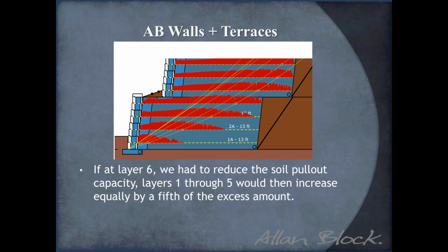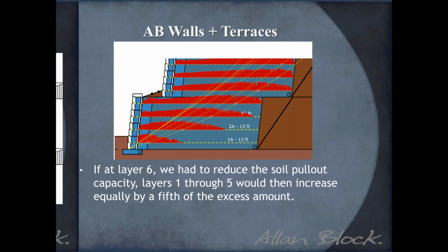So each one of the T requireds for the other 5 layers will increase by 100 pounds, so that all of those loads are put into that baseline solution, and now the new T required at these locations will reflect that additional 100 pounds. So it's pretty straightforward, I think. I'm hoping that idea is being passed along. That's how we're handling the end of the grid.